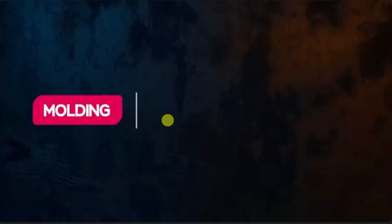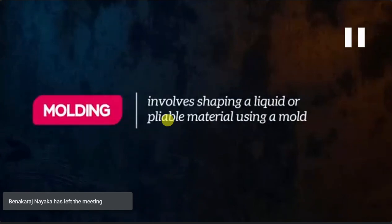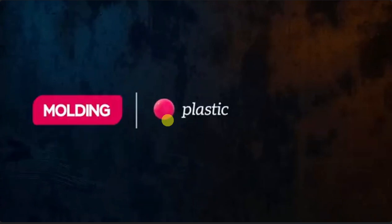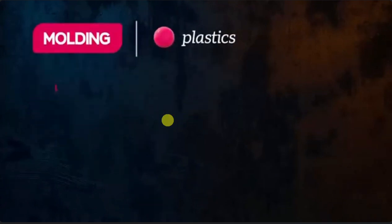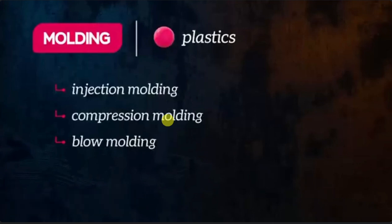The next type of manufacturing technology is molding of plastics. Basically, this is a technique we use to produce a product using plastic material. Here it involves shaping a liquid or pliable material using a mold. It is the same molding technology, but here it is meant for plastic material. There are three types of molding technology we follow: injection molding, compression molding, and blow molding. Let's look at the first two.